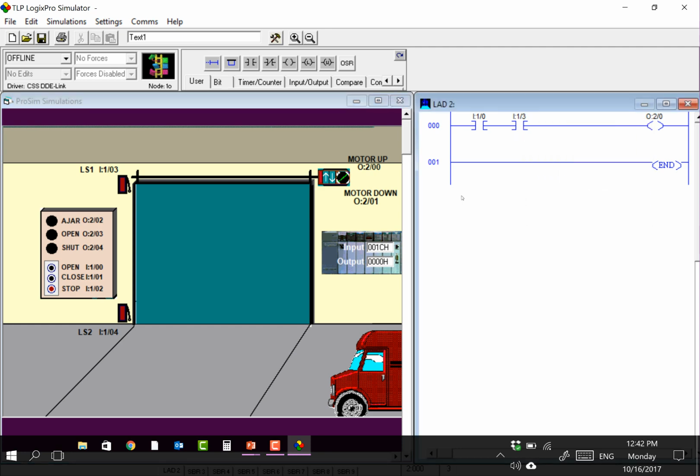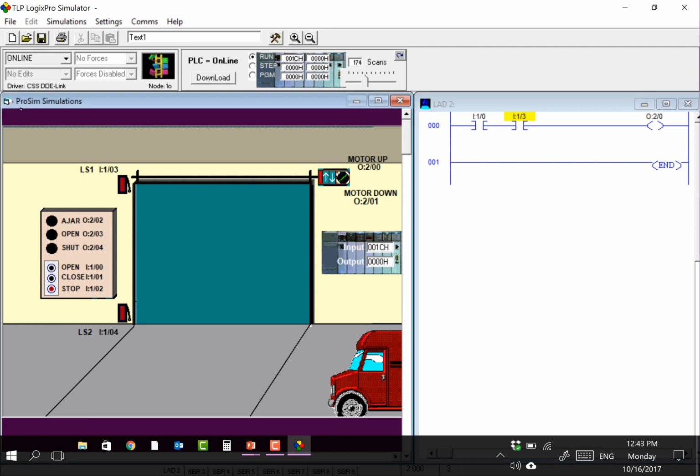Change to a normally open button. Let's see if that's what's going on. Sometimes when I'm running the simulation, it doesn't tell you whether it's a normally open or a normally closed switch. So this may be a switch there. So let's download it, run it. Okay, now it's highlighted. So yeah, now it's active. So now when I open the button, open it.